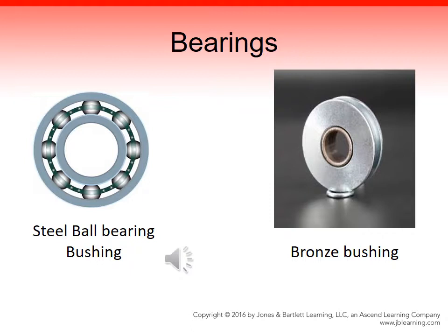In contrast, the ball bearing pulleys turn slightly more freely. Some are sealed to prevent contamination by dirt and grit. However, they are slightly more expensive, and they do not take stress such as sudden blows as well as the bronze bushings. Ball bearing pulleys are also damaged when the hardened steel balls dent the bearing races, and this is technically called brinelling.